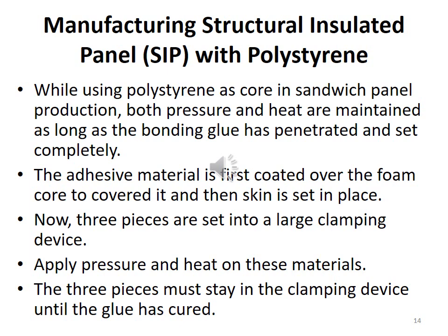The adhesive material is first coated over the foam core to cover it, and then the skin is set in place. Now the three pieces are set into a large clamping device. After that, both pressure and heat will be applied, and the three pieces must stay in the clamping device until the glue has completely cured.